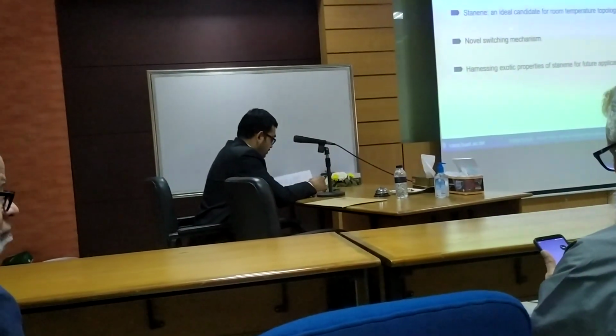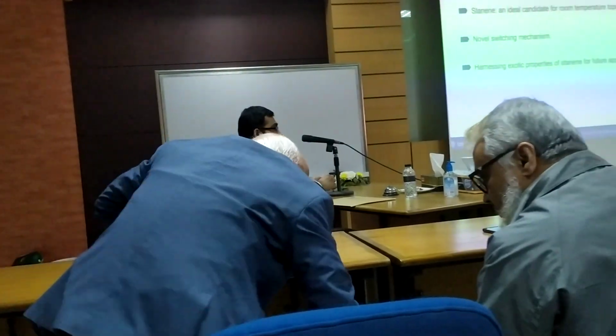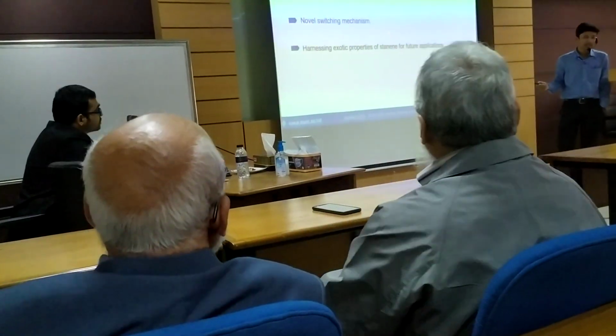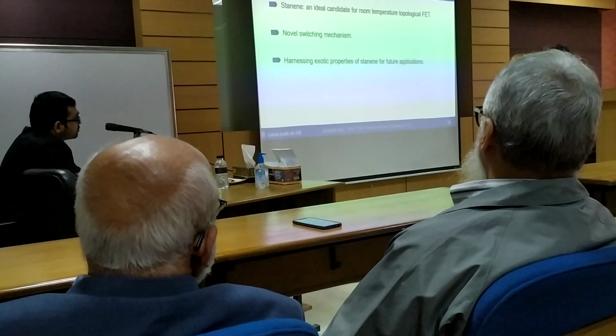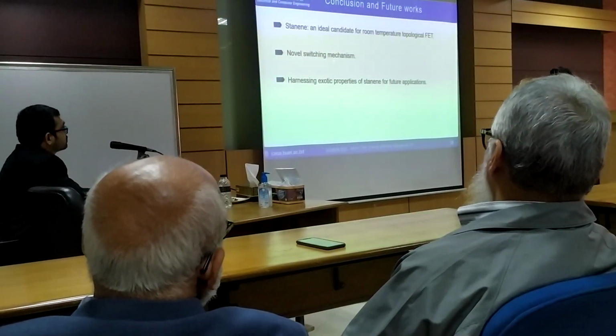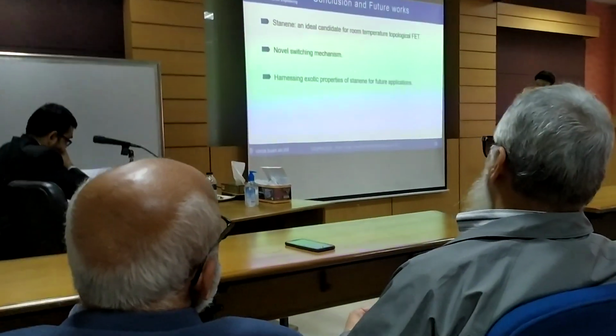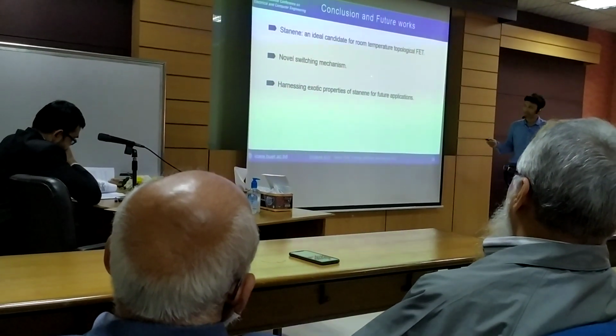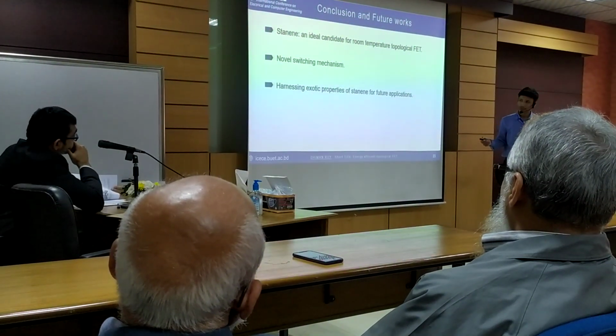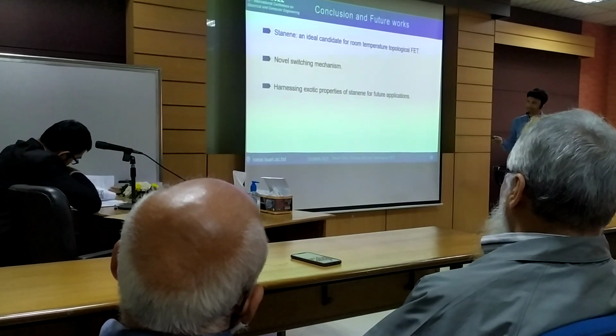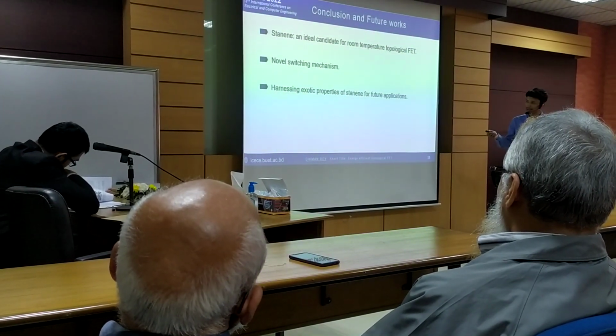So basically we have seen that this technique gives us an ideal candidate for a room temperature topological FET. That means dissipationless transport will be offered. And there will be a novel switching mechanism. That means by applying the electric field, we can change the corresponding band gap, and through this band gap variation, a phase transition occurs from the topological state, that means the on state, to the off state, the trivial insulating state.